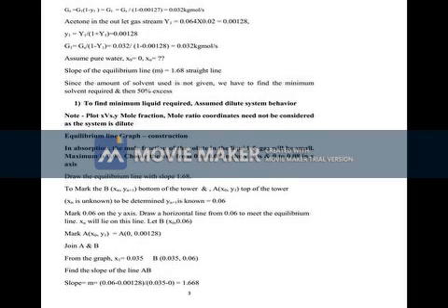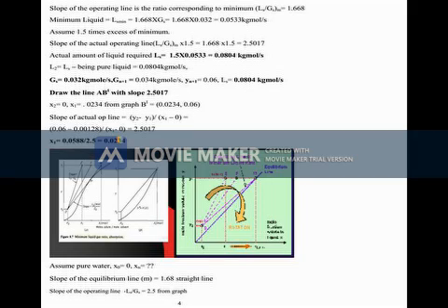Now you may be familiar. That is how much the pressure difference is between the lower column and the first plate and second plate, or in between two plates. You will get it in millimeters of water, and we have to check it against the atmospheric pressure. If it is a very low pressure drop, then we can say the design is okay.